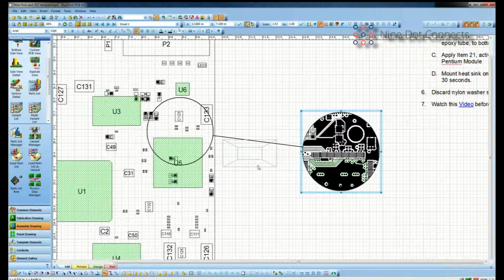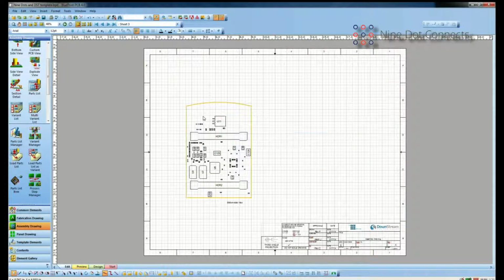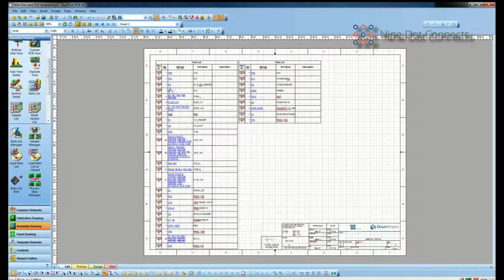Okay. I can also drop down things like parts list, of course, and in parts list, I can not only use parts that came in via the CAD system, I could import a parts list external to this data that might have some attributes that I want to add, or maybe in this case I've actually got it so that it's going to bring in the bin number for me when I import it.